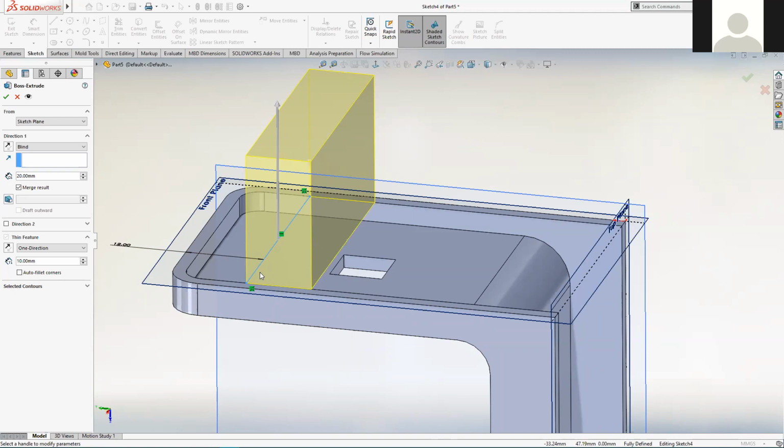It says, you haven't created a closed boundary, so I can't fill in the boundary with solid material because you haven't created one. So my second solution, other than modifying the sketch for you, is to just add some material to one side of the line that you've supplied me with. What that's called is a thin feature.